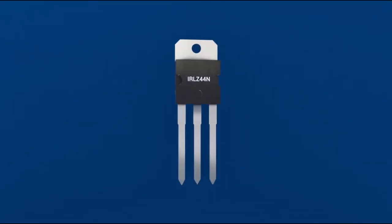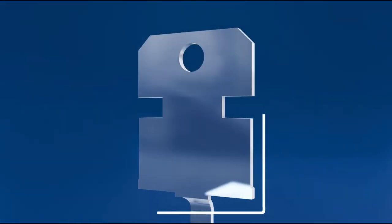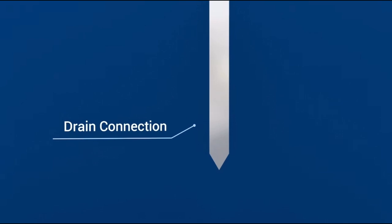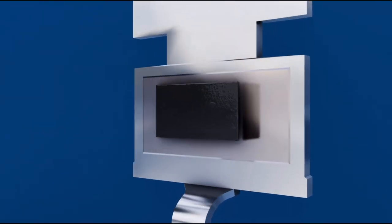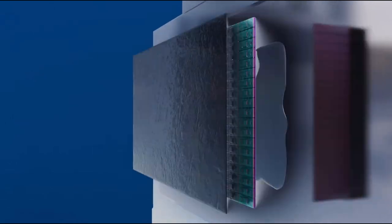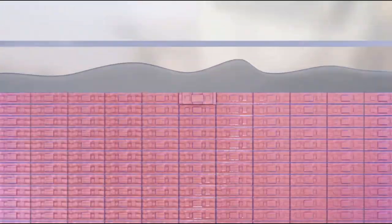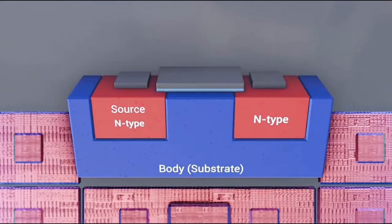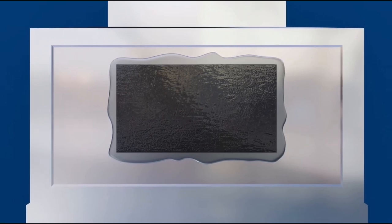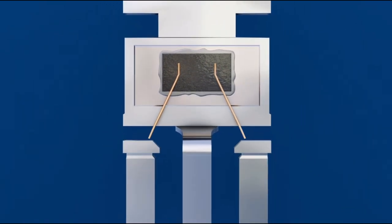The anatomy of a MOSFET. Inside its black epoxy package, a power MOSFET is mounted on a copper lead frame that serves as the drain connection and a heat-spreading plate. On top of that copper plate sits the silicon die, whose underside is soldered directly to the drain. The die's top surface carries two heavily doped regions, the source and the body, which are electrically shorted together under a single metal pad, and the pad, often with multiple bonds, is wire bonded to the source pin.